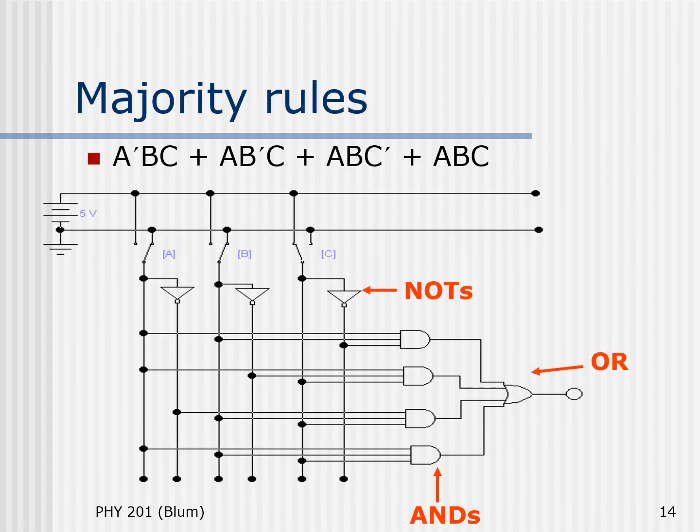So here we're going to build this majority rules expression with logic gates. Okay, let's start our focus with the battery. There's a short end of the battery and a long end of the battery. The short end is also connected to ground, meaning that it is 0 volts. Then the long end of the battery is 5 volts higher than that. So the lower horizontal line corresponds to a level of 0 volts, and the upper horizontal line corresponds to 5 volts.